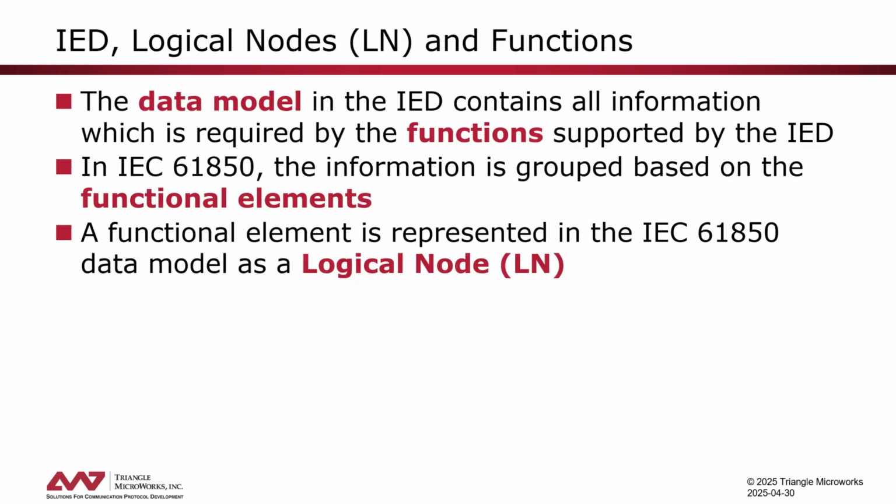As a quick reminder, the data model in IEC 61850, the data model of an IED, basically contains all the information that is required by functions supported by the IED. As you have learned already in the first part of the webinar, that information in 61850 is typically grouped based on the functional elements that we have in the device.